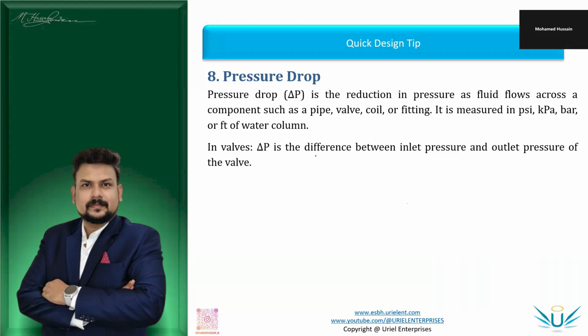So which pressure drop are we going to take? In order to size the valve, we are going to take the pressure drop inside the valve, because if the water flow is coming and the valve can handle that pressurized water flow, then it will give good, stable control.